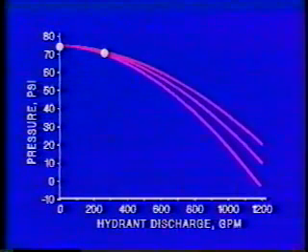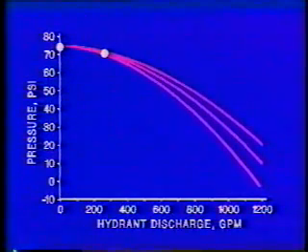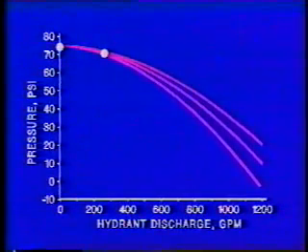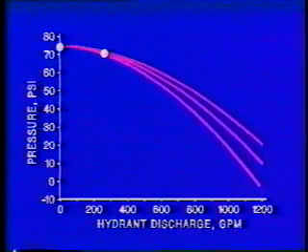A common mistake when conducting a fire hydrant flow test is to not open up enough hydrants to get a significant drop in pressure at the residual hydrant. You should get a drop of at least 10 psi at the residual hydrant, preferably 20 psi or more. The problem is that if you don't get enough of a pressure drop and you try to use the results to extrapolate down to 20 psi, a small error in reading any of the gauges will be magnified.